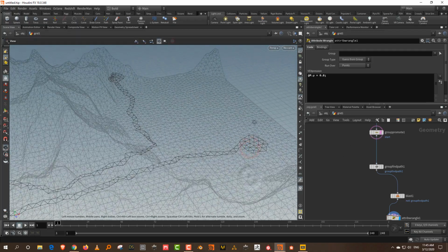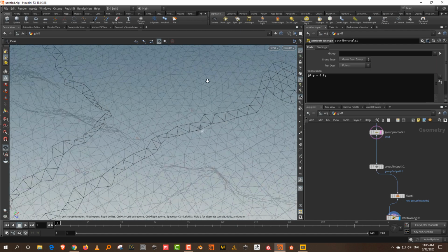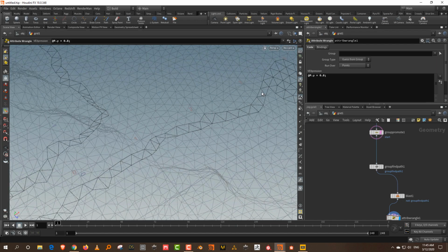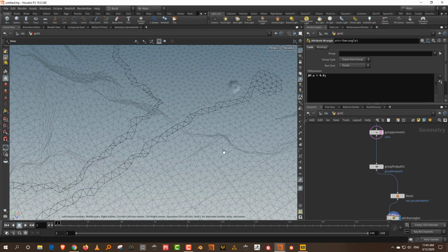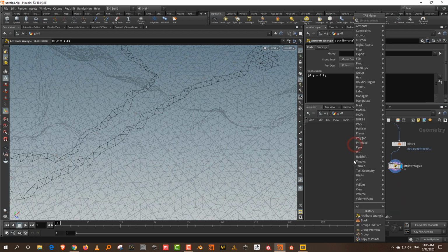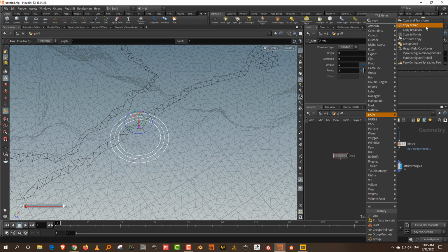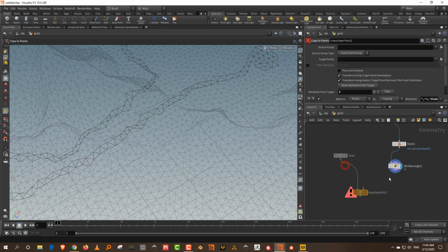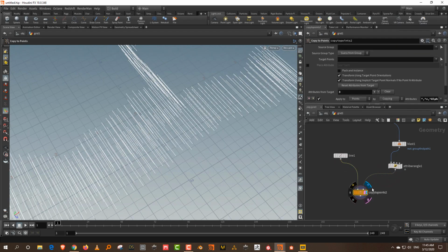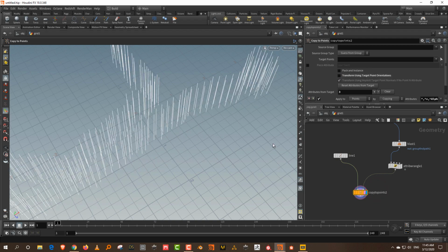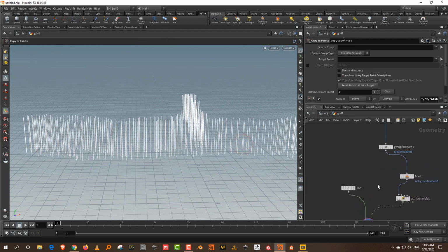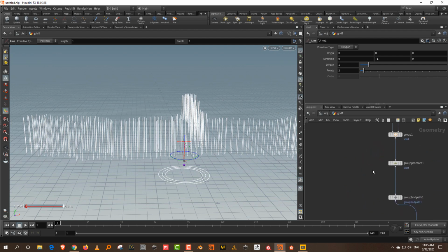And then I want to generate, like if you want, you can just generate pillars on the side of this, which should be okay. So what I can do is I can just take a line and point it in the negative. So direction should be -1 and just do copy to points. So you can take copy to points and this comes in here and just turn off transform using target point orientation. So they'll point downwards like that. And that's pretty much it.